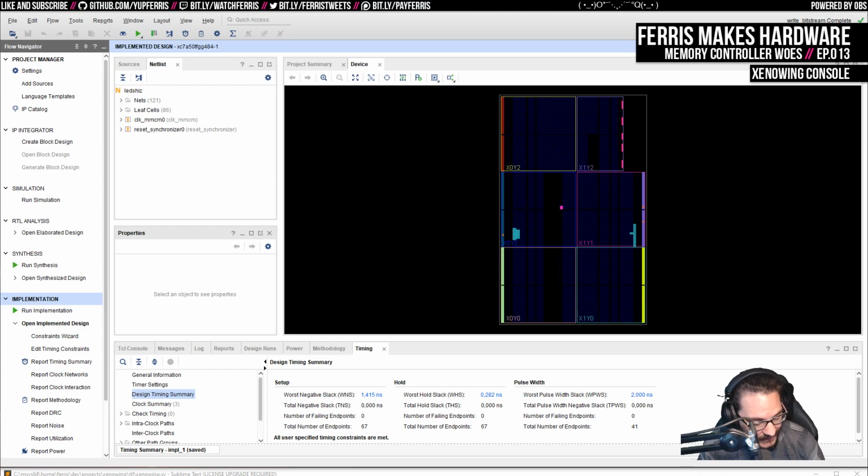But anyway, I was able to fix that just by reducing the clock rate, because I don't even need the thing to run at 150 megahertz. The only reason I was doing that was to interface with the memory controller without doing clock domain crossing. So I dropped it down to 100 megahertz. But then the other consequence of this is that now the system has a 160 by 120 frame buffer in order to actually fit 2 buffers in memory. And so I kind of retimed the design to actually work with that. So the nice part is I have a working design now on my Max 10 board with no timing errors. It seems to be super solid.